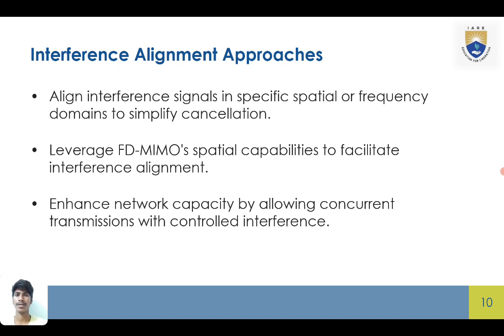Interference alignment approaches align interference signals in specific spatial or frequency domains to simplify cancellation. Leverage FD-MIMO's spatial capabilities to facilitate interference alignment, enhancing network capacity by allowing concurrent transmissions with controlled interference.